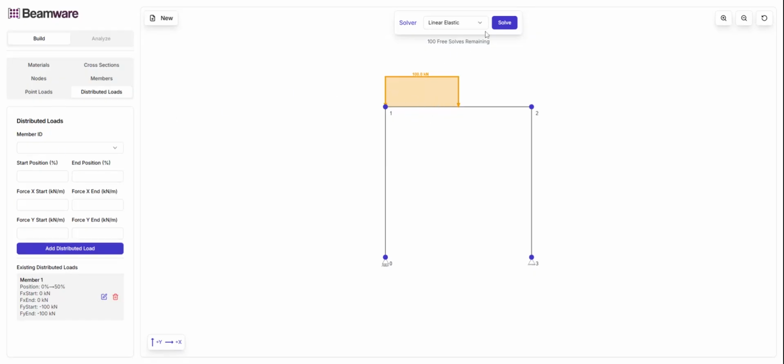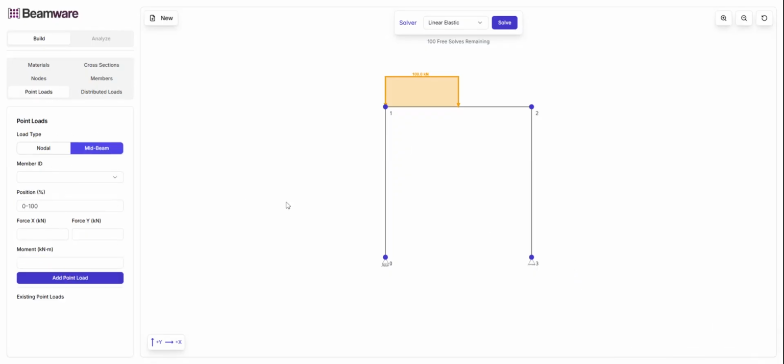And then I'm going to go try to solve it. However, you're going to get this analysis failed to solve structure. So this is not going to run if you don't have a valid case, for example. And the reason is, if you guys remember, basically this is right here, a truss element. So there's too many releases. This is not stable right now.